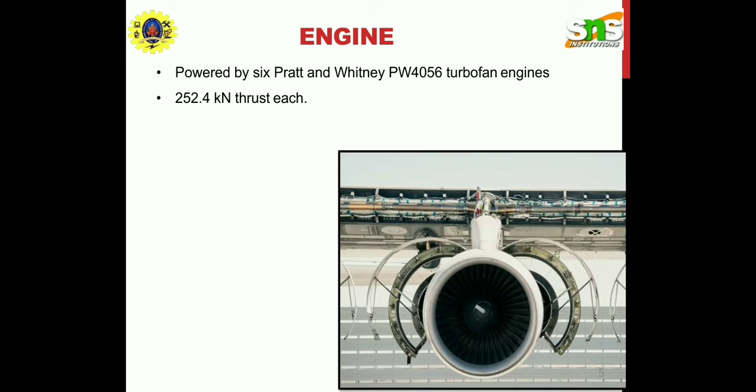Outward flow type increases the energy level of the fluid and vice versa. Due to the continuous changes in direction, several radial stages are generally not used. A centrifugal pump is an example of a radial flow turbo machine. Then there is the mixed flow turbo machine, such as a Francis turbine.